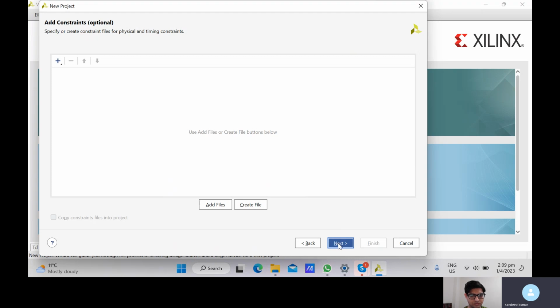Basic constraints are like this: let's say you have hardware, so it's a hardware design. How will it connect on the chip? You have to drive something from the inputs, and capture the outputs. There will be pins on the hardware, so we map the pins of the design to the hardware using the constraints. Which pin is connected to your design input, that kind of thing we write here. Also we write the clock constraint, which relates to the speed at which you want to run the hardware, and that gives the performance.